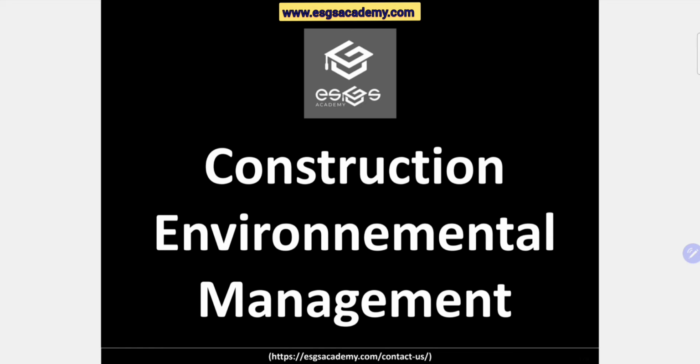The main goals of the CEMP are to specify the roles and responsibilities of personnel involved in all aspects of the construction activities, identify the potential environmental impacts and the mitigation measures that will be used to address them, and establish the procedures for audit, monitoring, and inspections, specifying the training, record keeping, and documentation requirements for the construction project.